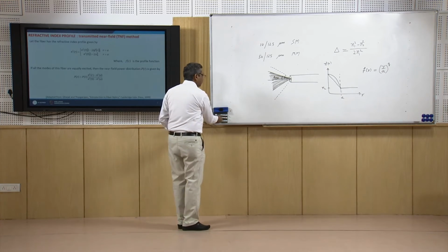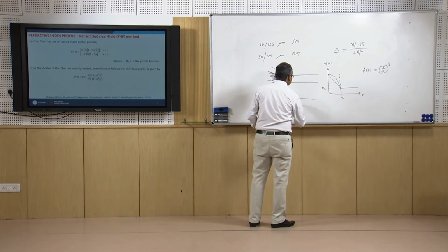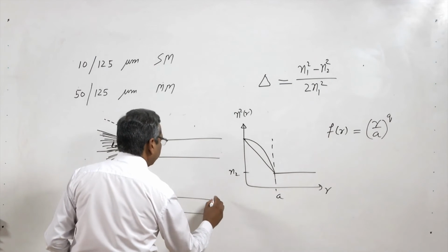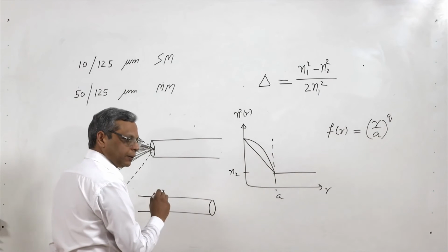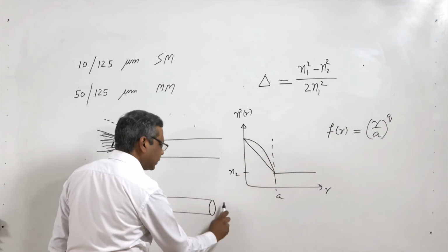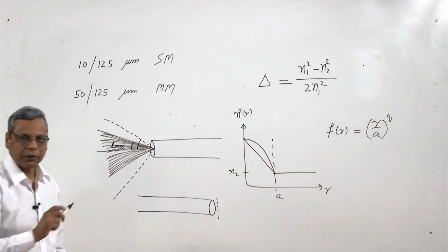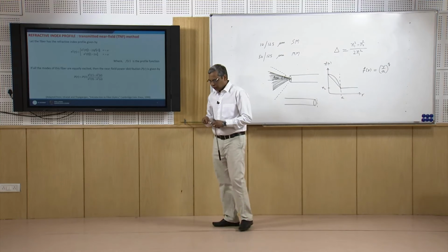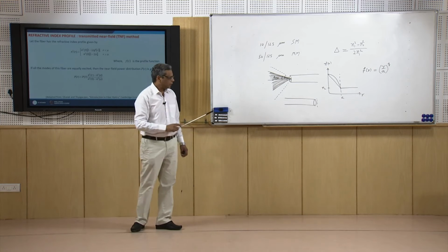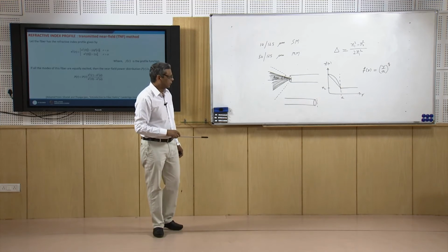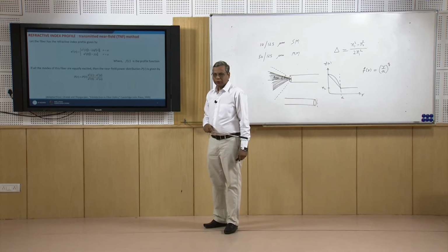Near field distribution means you launch light into the fiber, and at the output end you capture the light coming out of the fiber as it just comes out, very near to the fiber, so that the Fresnel number is much smaller than 1, that is the distance from the fiber is very small, within a couple of millimeters.